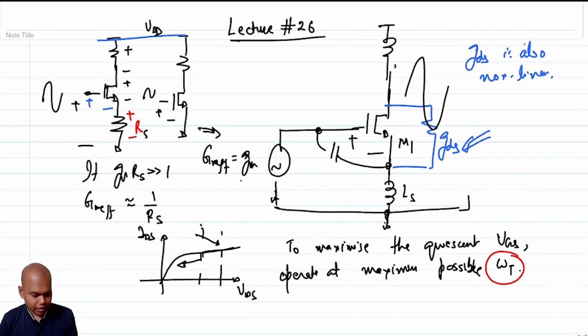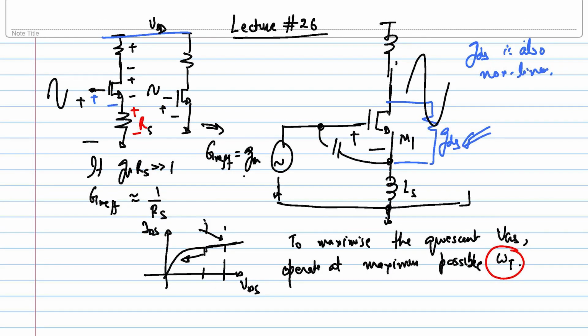till now it seems like negative feedback cannot really solve the problem because of reasons that we have talked about. The only handle seems to be to increase the VGS, quiescent overdrive. Then it might seem that we have very limited options to improve the distortion performance of an RF amplifier, right? It might seem so, but that's not the case.